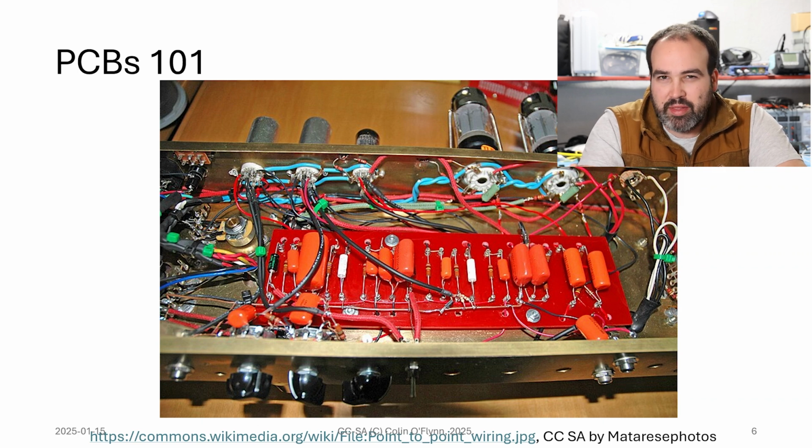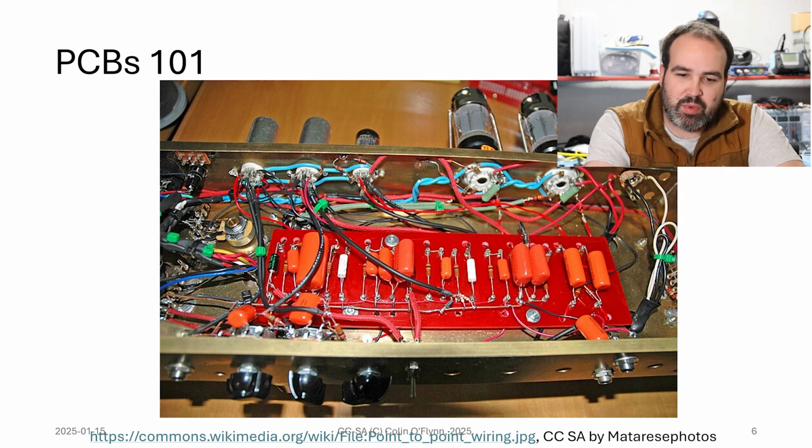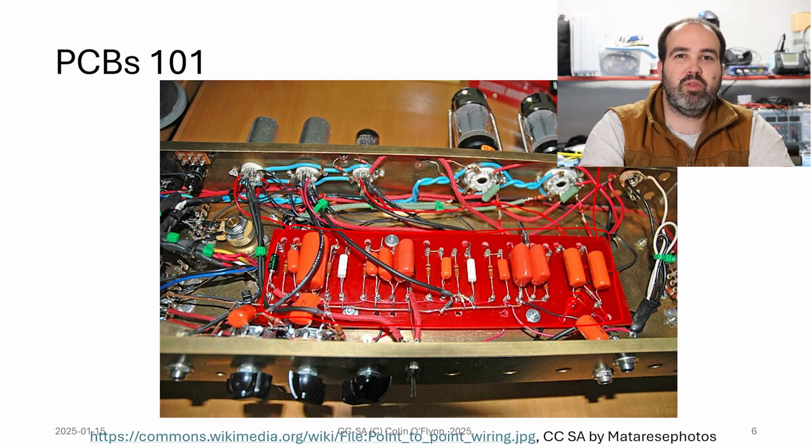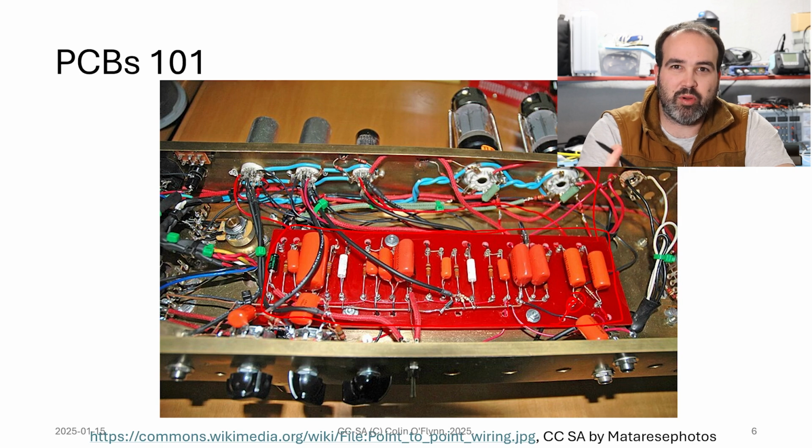The next step beyond that, there's many steps, but we have boards like this where we have a board with the parts on it, but there's not really traces interconnecting them. What they do have though is an isolated board with pegs, and there's wires that are wrapped around them. So quite complex boards can be made with this wire wrapping. You can make good prototypes with it. I've made a bunch over the years of this type, and you can do a lot of pretty complex boards with wire wrapping techniques.